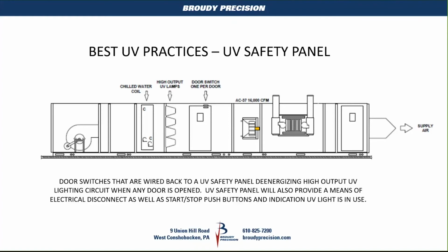Another thing we just started recently playing with is carbon activated systems in combination with the UV 213 germicidals, and had a lot of interesting results with it. Very effective. Efficacy is incredible. What we're finding is we also don't need to run these things 24/7, and you've got to be careful creating ozone in certain types of UVB systems, which are notorious for creating ozone. That's sometimes an unwanted derivative of this. So you have to use cold. That's why understanding the saturation factor and the outside air changes are critical.